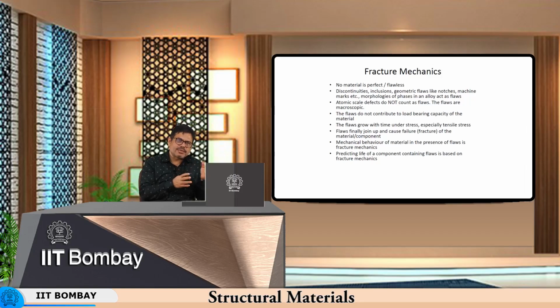crystallographic defects like dislocations or point defects like vacancies or interstitials and so on, but we are not talking about those defects. We are talking about flaws which are macroscopic in nature, which are left behind or which are generated because of impurities in the material, intermetallics getting formed by impurities combining together, and which generally deplete significantly the load carrying capacity of a cross section.